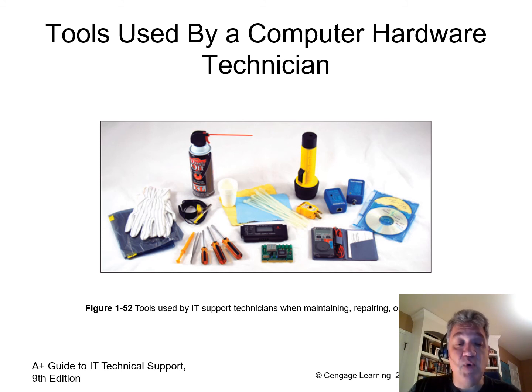For example, maybe you have a fan that fails inside of your PC. Well, it may be a good idea before you replace the fan to check to make sure that the socket that it's plugged into is actually receiving enough power.